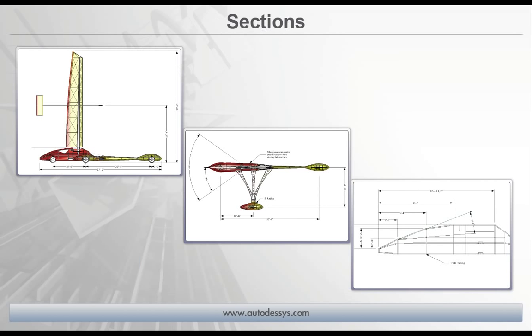Okay. Now we do have a dedicated section tool, and what that does is it works sort of like the clipping planes, but it's just a single plane. You move it through, and when you say you're done, it automatically cuts the section at that location, specifically for cutting a Boolean section cut through your model using any plane.